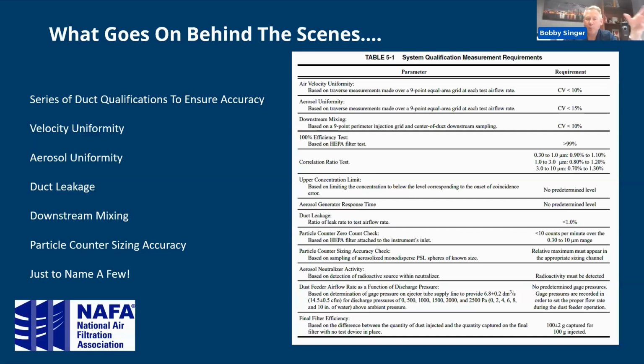The same with the aerosol. When we generate aerosol, we have to prove that we're getting basically the same concentration in the top corner as we are in the bottom corner. It has to be evenly distributed. We have to show that the duct doesn't leak. We pressurize the duct to make sure it's not leaking.